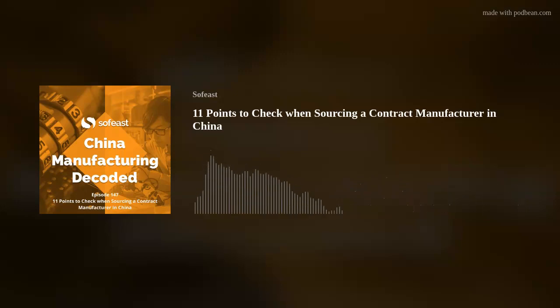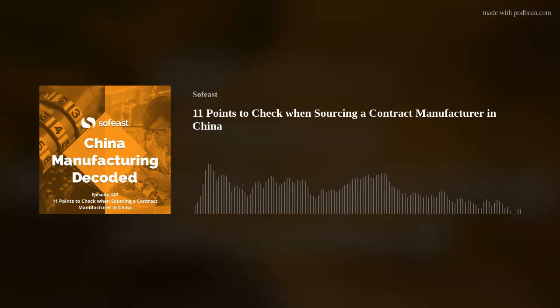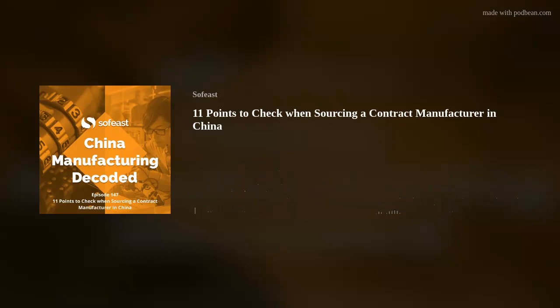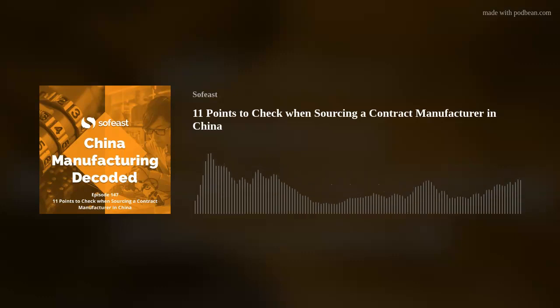So that's really important. When it comes to compliance, again, do you need them to already be aware of what actually applies to your product? And we're talking about electronic products. So, in the US, FCC, obviously, UL, for some products, in the EU, anyway, RoHS, and maybe LVD, maybe RED, which includes some others. There's a number of things that apply, right?